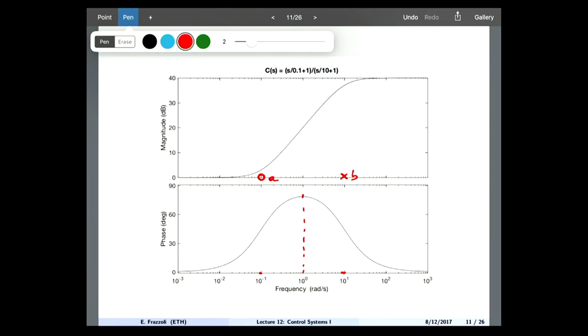Right, so it's kind of like the mean of the two frequencies of the pole and the 0 on the logarithmic scale. What do you call that thing? It's actually the geometric mean, okay? So this is the geometric mean. This is square root of AB, okay? Which you can verify is exactly 1/2 the sum of these two when you consider the logarithms, right? So the sum becomes the product, 1/2 becomes square root, okay? So it's exactly the same thing on the logarithmic scale, and corresponds to just the midpoint on the logarithmic scale.